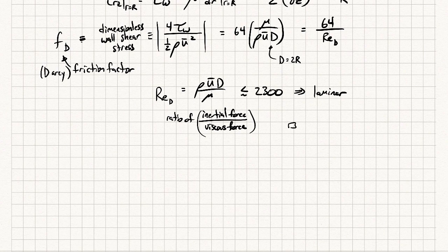So imagine you have some little piece of fluid here. When I say inertial force, think about that almost like the momentum of the fluid, that if you push on a piece of fluid, it'll carry for a long distance if it has a large amount of inertia associated with it. So imagine you have some piece of fluid, and let's say we perturb it. We have a flow, and we just give it a little perturbation up or down. If we have large viscous forces, then that perturbation will get damped out, and eventually the piece of fluid will start to go horizontal again, because the viscous forces are dampening out any perturbations. But if we had large inertial forces, and then we perturb it, they're not going to get damped out. They could grow, and this could end up becoming quite chaotic. If we have a large amount of inertia and we're not dampening out the fluctuations, it could just continue.